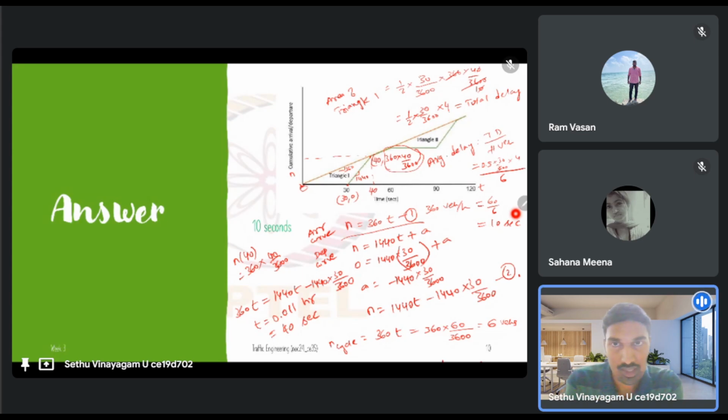So we have 6 vehicles that are coming in, right? Each vehicle experiences a different delay. The vehicle that came exactly at the start of the red experiences the longest delay, so it will wait for the whole 30 seconds. The vehicles that arrived later will be waiting for a smaller and smaller amount of time, and the vehicles that came after the queue dissipated have zero delay. But on average, the 6 vehicles have a 10-second delay, right? So that's all that we have to do for this particular question.